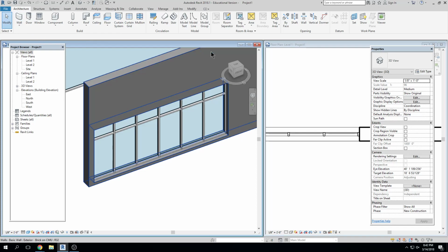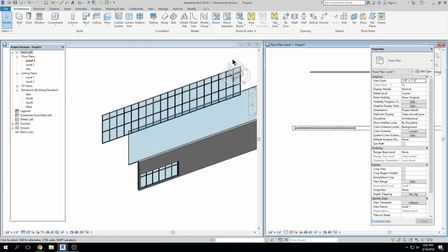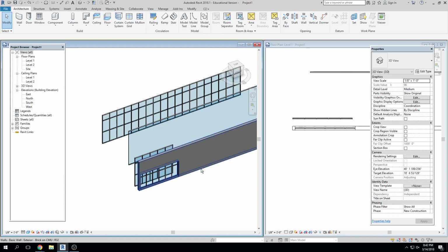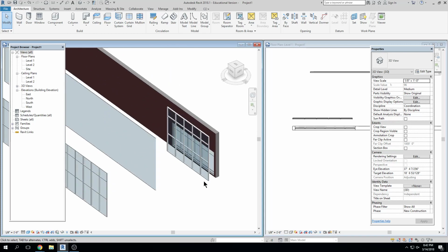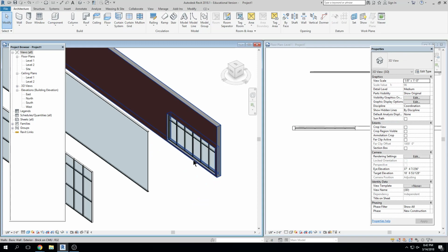So if I wanted to draw just a storefront wall, I'm going to come up here to wall, architectural, storefront, click, click, and obviously just like I did back here, I can create a self-standing storefront piece here, right? Although I don't know why you would want to have a piece of storefront just kind of hanging out, right? Anyway, but you can, if you'd like, do that.